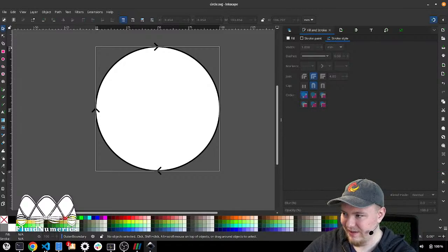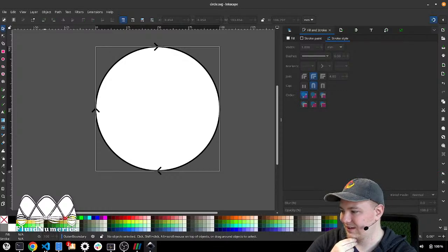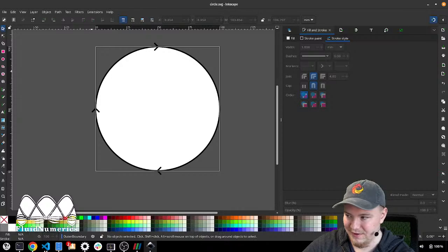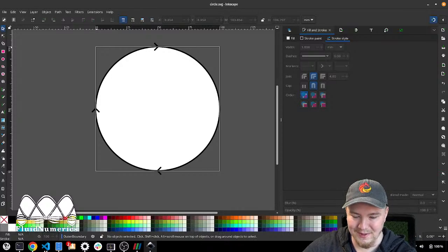This is essentially because in Inkscape, I have gone into the settings and set my units and my origin to be in the bottom left. Even if you set this, no matter what, Inkscape will think of drawing paths with the origin being at the upper left.